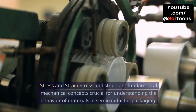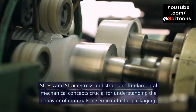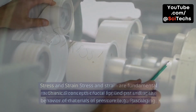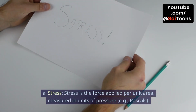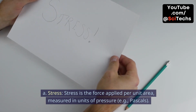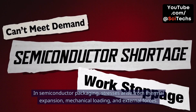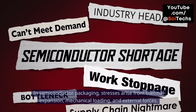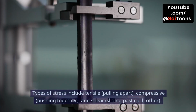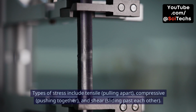mechanisms. Stress and strain are fundamental mechanical concepts crucial for understanding the behavior of materials in semiconductor packaging. A. Stress. Stress is the force applied per unit area, measured in units of pressure, e.g., pascals. In semiconductor packaging, stresses arise from thermal expansion, mechanical loading, and external forces. Types of stress include tensile, pulling apart, compressive, pushing together, and shear, sliding past each other.